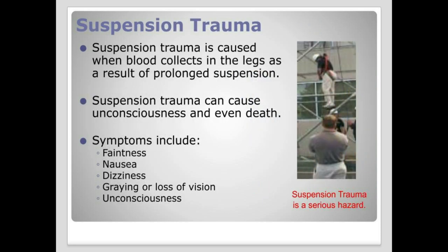Suspension trauma. Suspension trauma is caused when blood collects in the legs as a result of prolonged suspension. Suspension trauma can cause unconsciousness and even death. Symptoms include faintness, nausea, dizziness, graying or loss of vision, and unconsciousness. Suspension trauma is a serious hazard.